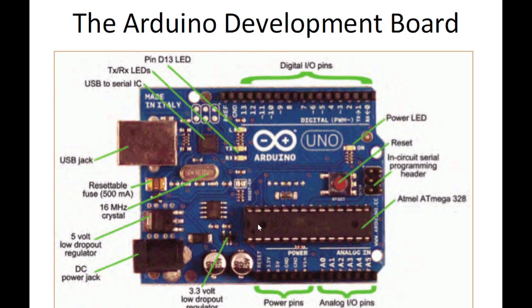all students to know is that this IC package is called DIP. DIP stands for dual inline package. Why? As you can see, it's line number 1, line number 2. So it's dual inline. As you can see, they're both inline. So dual inline package, also called a DIP, and it's a through hole IC used for any IC of